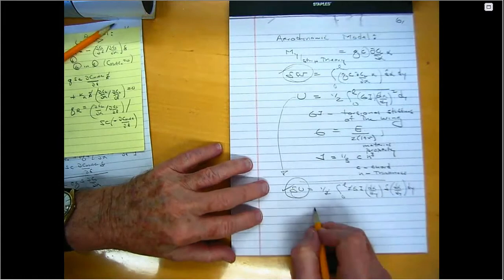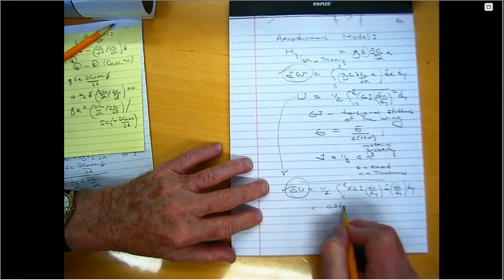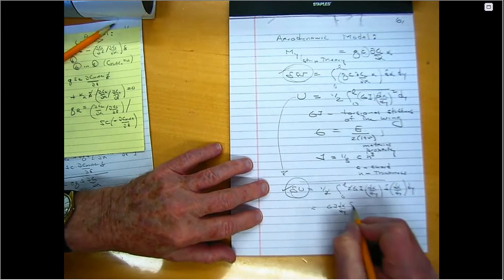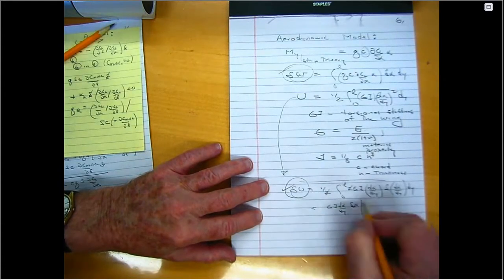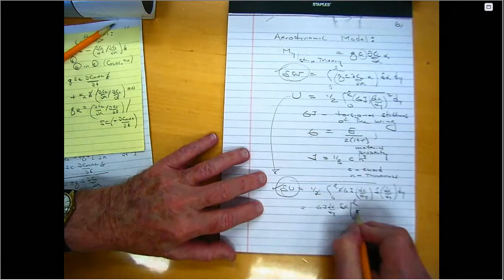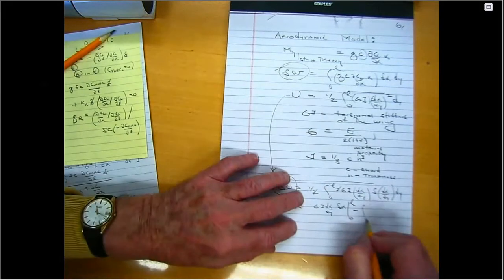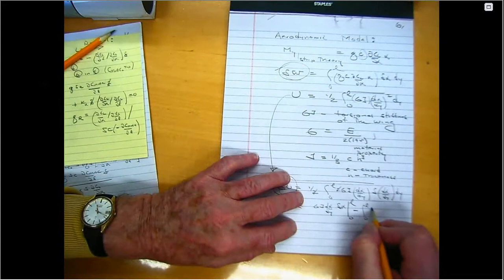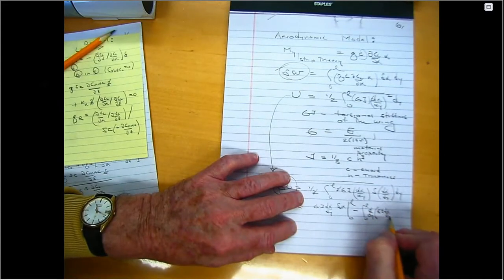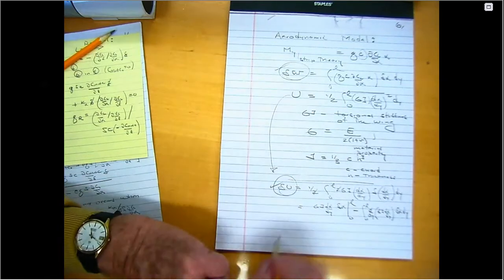I'm going to integrate this by parts, and if I do that, I get GJ d alpha dy times del alpha evaluated at the limits. And there's always a minus sign when I integrate by parts, right? And then I have a minus, integral from 0 to L, of the derivative with respect to y of GJ d alpha dy, times del alpha dy. That's what I get by integration by parts.